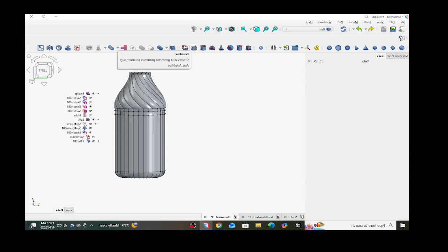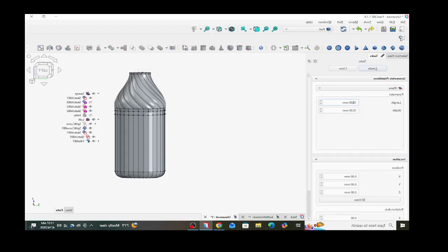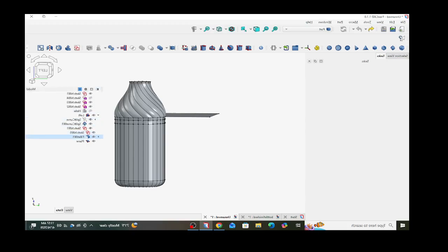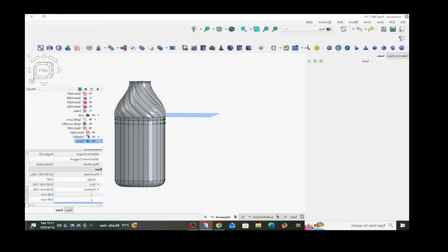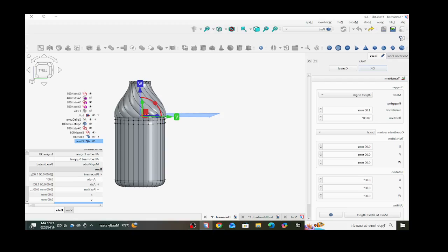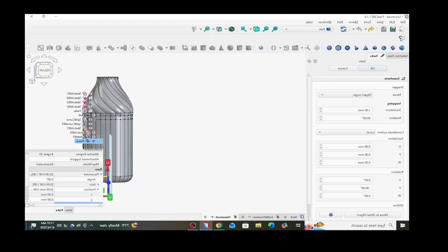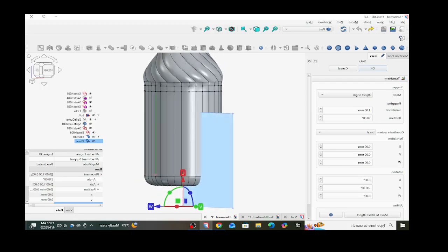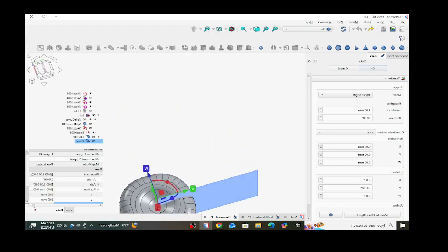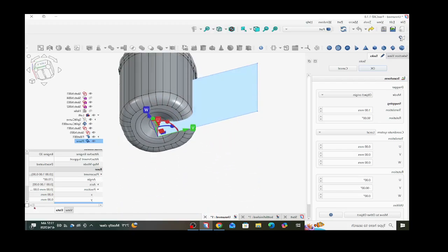There's some quirks in FreeCAD, of course, that you get used to using. It's a great software. I love it, but try this again. Good. Click on Attachment Editor instead of Transform, which is what we want. We want to make sure the rotation angle is set to 90 degrees. I'm going to rotate it up. So we're perfect right here, is what we want.